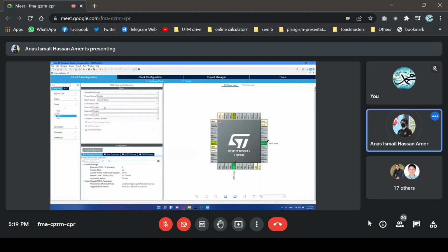Again, this is the same setup that we used yesterday. If you go back, we'll put the prescaler, for example, as 64 or 640. Then we'll calculate the period so that we get a 1 millisecond interrupt.